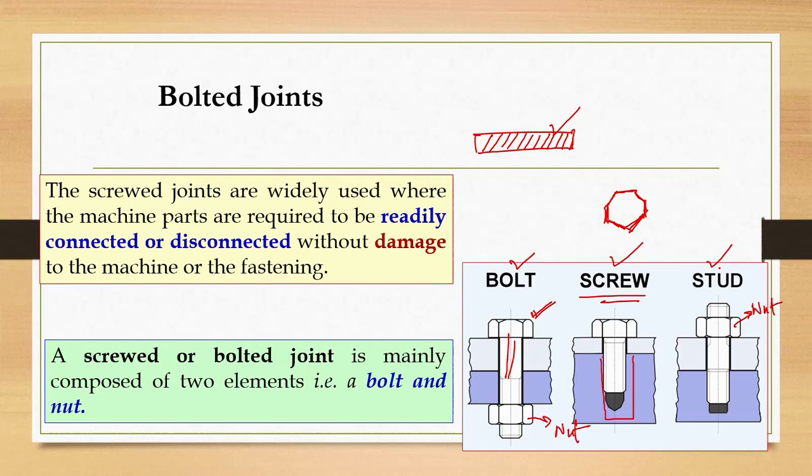If you want a bolt size of, let's say, 10 mm, and you want a bolt shank length, where the shank is the body of the bolt, say of 7 feet, these bolts are not available, because standard lengths of 10 mm bolts are generally not more than 3-4 inches. Now instead of using standard bolts, you can use studs. Studs are long threaded cylinders. They do not have any head, but you would go to any hardware shop and ask him, I want a stud, I want a threaded cylinder,